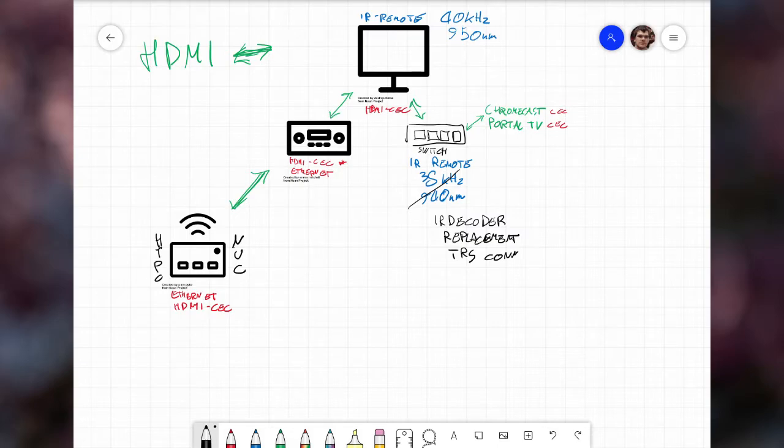But it just has the normal style IR decoder, which ignores the whole frequency modulation, the whole wavelength and everything. It just has a signal modulated there, and just sends the pulses. You'd only care about the pulse length, which makes the whole thing easier to implement, except it needs an optocoupler. But that one is solved. So this one will have its own audio jack with TRS replacement.